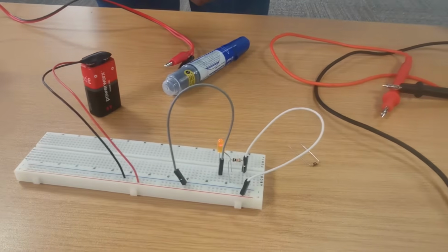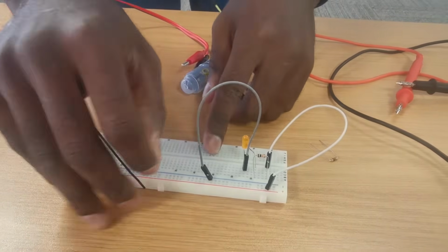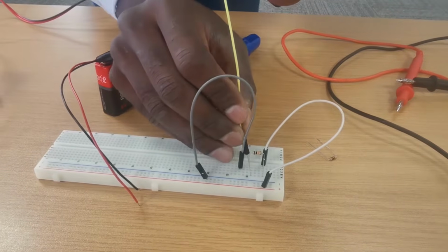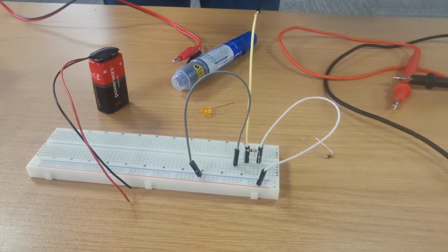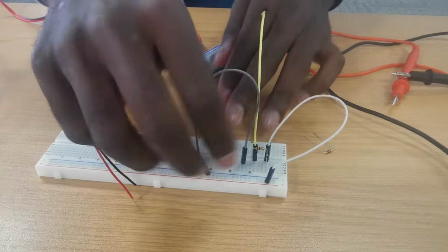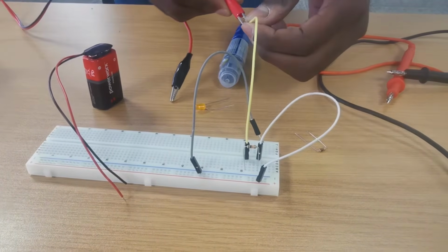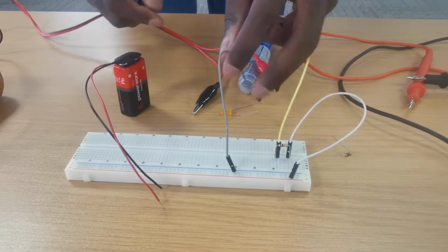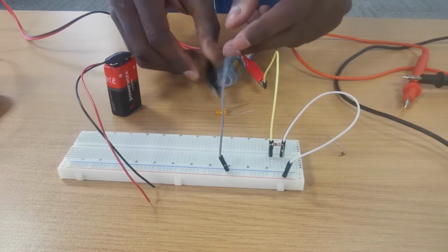And how I'm going to add it, I'm going to take this out. So I take my source out, I take my diode out, and then after my resistor, I'm going to put a cable here. For the positive of the ammeter, I'm going to put a cable, for the negative of the ammeter, but that can go straight to the negative. So then I'll take this positive, connect it there, I take the negative, and I connect it to the negative leg of the ammeter.